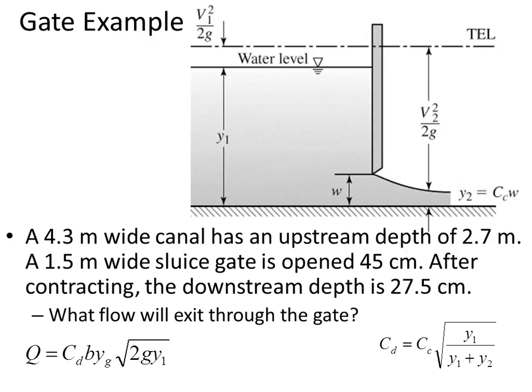So then multiplying that coefficient of discharge, the area of the opening, and then remember square root of 2GH is sort of how we calculate the velocity through an orifice. Essentially, we're treating the gate as an orifice, and so this is really just the orifice equation. The velocity is the square root of 2GH, and we've got an area and the energy, accounting for energy losses with the coefficient of discharge.